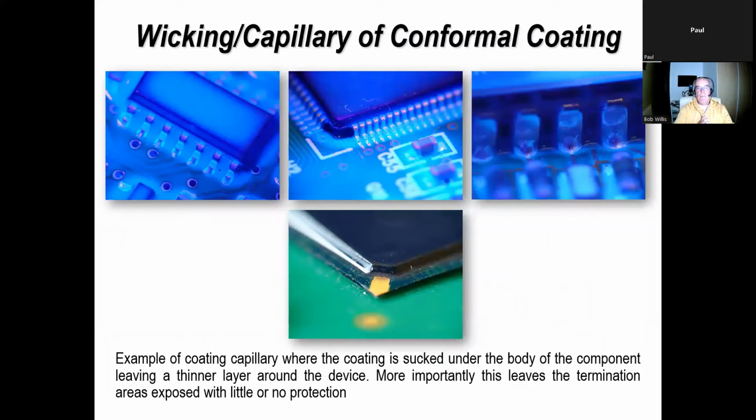Now, if we're talking about most components, there's not a problem with conformal coating going underneath the part, provided that you've checked the expansion coefficient, the actual expansion rate of the material you're using. Because if you've got a board assembly and you've got something like a BGA, an area array package, and you've got a conformal coating which goes underneath it, if you've got a large expansion and contraction taking place during the operation of your device, you can deform the solder joints and you can break the solder joints. And I've seen it happen. It is a reality. But all you need to do is check with your supplier the material you're thinking of using and look at the expansion coefficient of your board material, your solder joints, etc. So that's all you need to do to make sure they're compatible. You may do your own environmental tests, but check the basics first of all, and then that shouldn't be an issue.